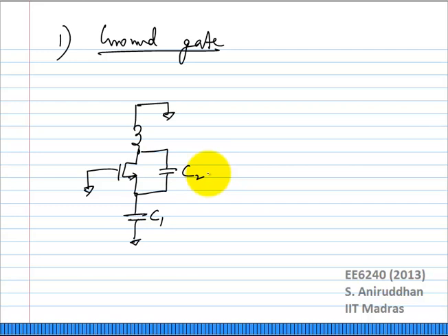Correct. So first of all you need to have a bias current for the transistor, so you will need to add a current source here. What else? Power supply needs to go in, and power supply can actually go in here, VDD, and you have an oscillator circuit, right?